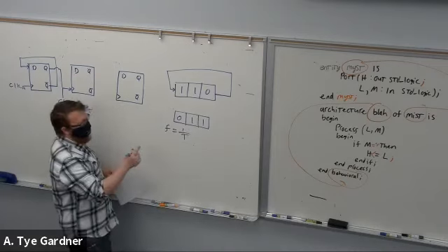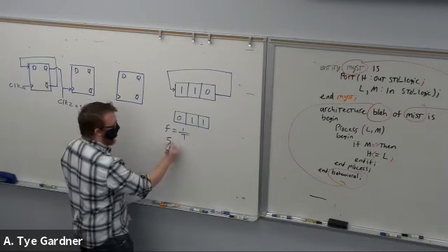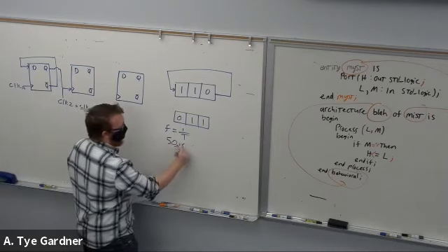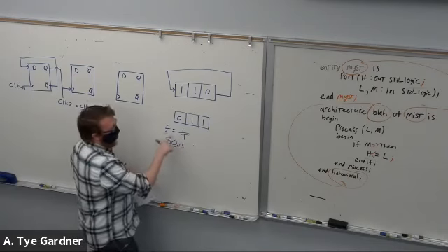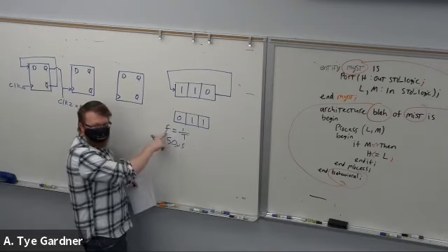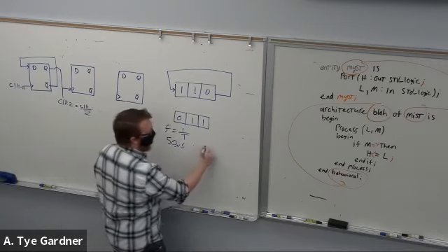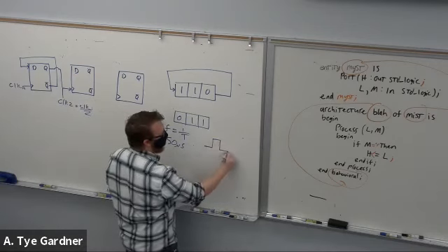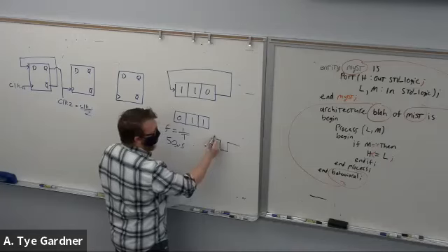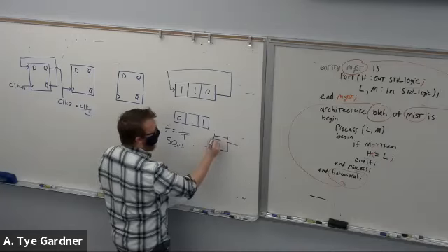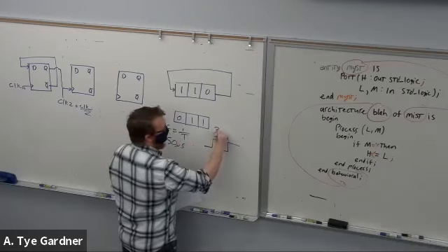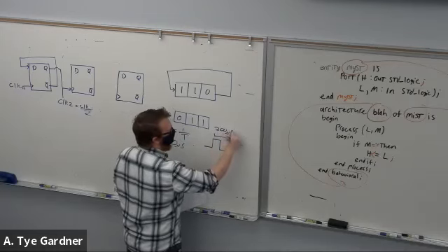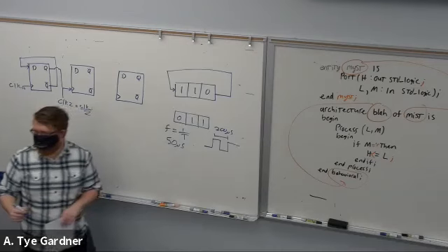I said there's a 50 microsecond clock to Q delay, and I said F is 5 kilohertz, which means the time period on the clock, rising edge to rising edge, at 5 kilohertz is 1 divided by 5K, which is 200 microseconds.